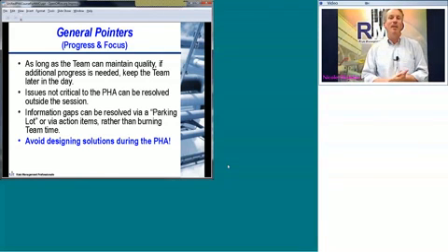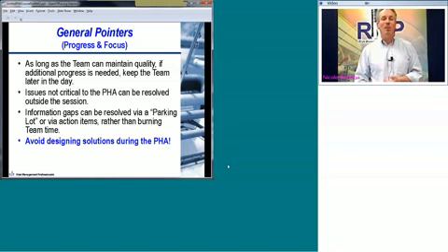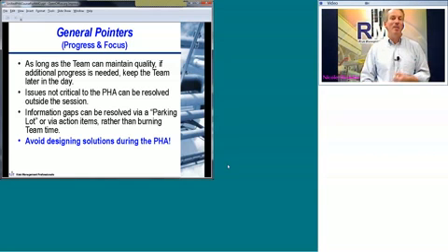It's so that the entire team can see what sort of things need to be followed up on, and always put a person's name on it. If you want something done by the end of the HAZOP study, and it doesn't have a name on it, chances are, with the HAZOP study and their normal job duties, it's not going to get done unless a specific individual is assigned.